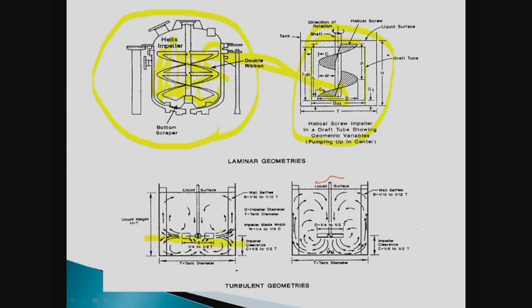If you're filling a batch of bottles from a batch, as soon as the liquid level reaches the agitator, you have lots of problems that can happen. You can have foaming, splashing, bubbles, not bubbles, but foam. When it drops below the agitator, this whole area is essentially no longer being mixed.